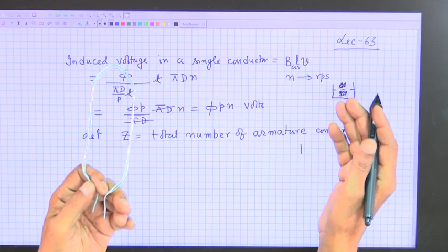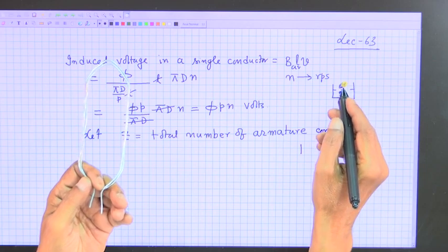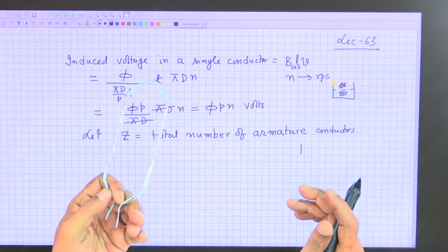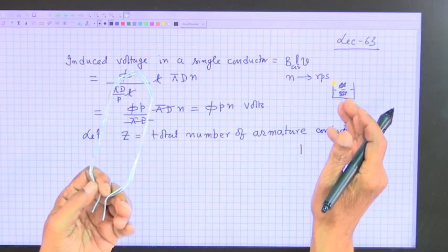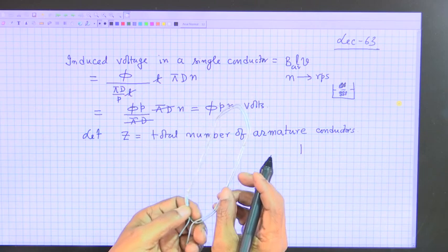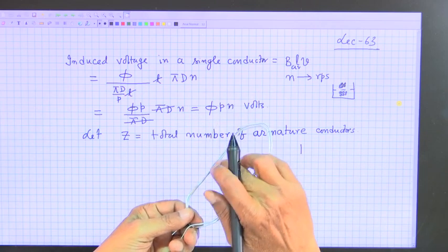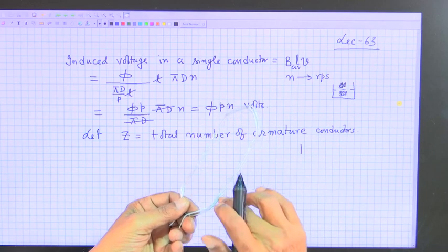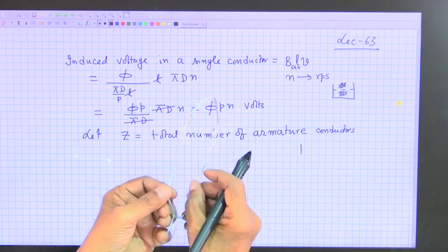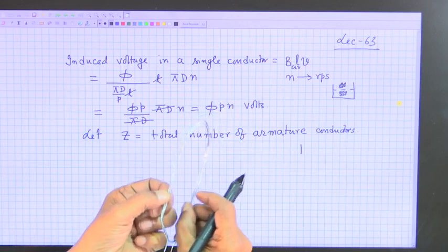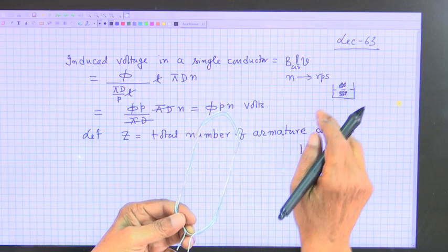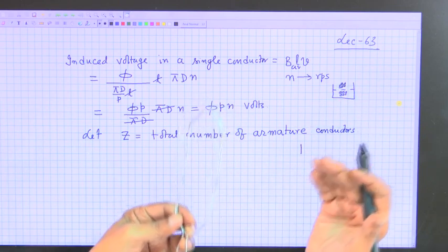So, multiply each coil with that multi-turn number. If it is a 2-turn coil, multiply with 2, then with another 2 for this one. So, total conductors means these conductors also, because they will become seat of EMF, they are having same velocity, same flux density they will see. All the coil sides in a particular slot will have same voltage B average L V.